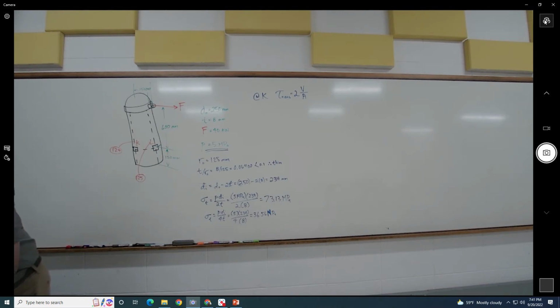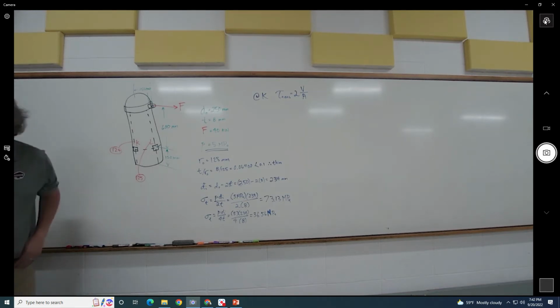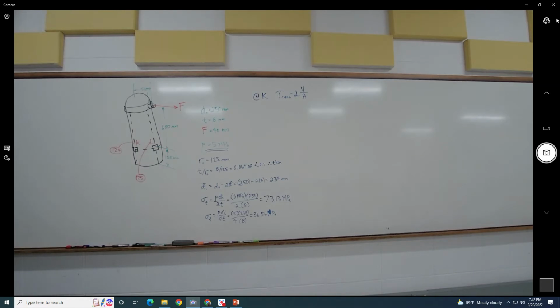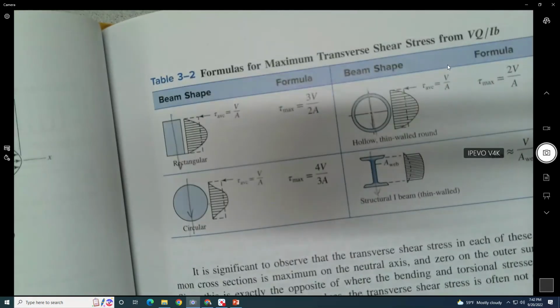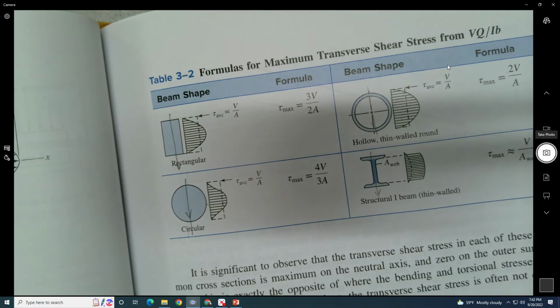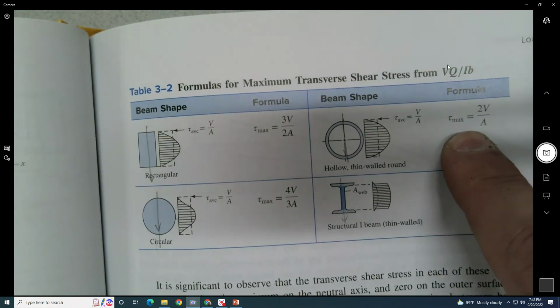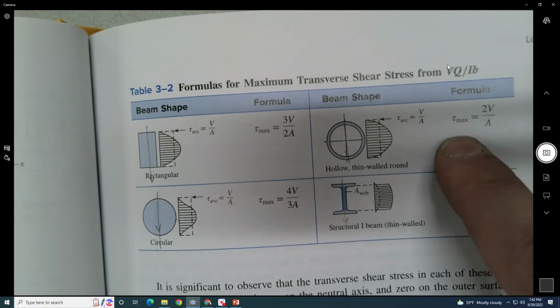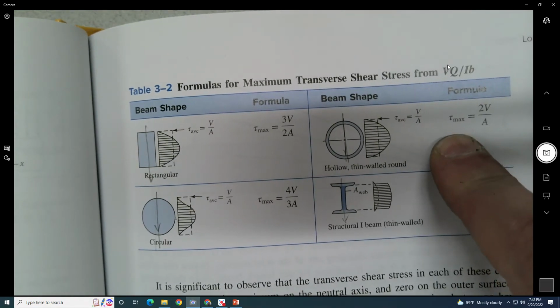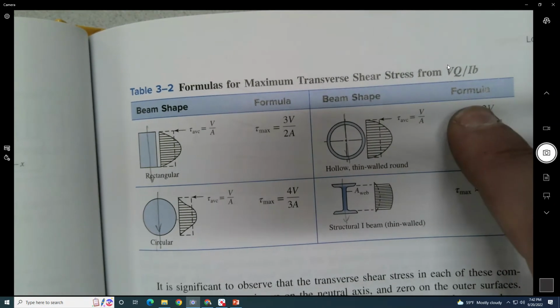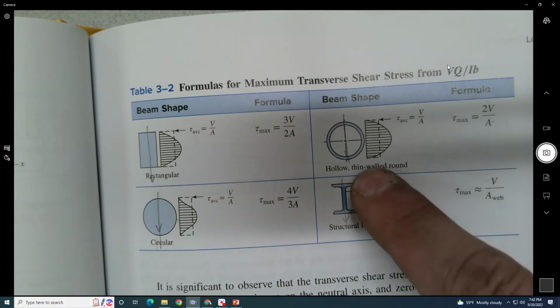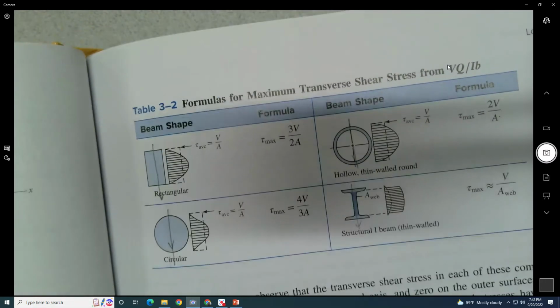So what does the subscript T and L stand for in the shear? The T is for tangential, which is also known as hoop. I like the name hoop better. But we got the maximum shear here. By the way, the L is longitudinal. So we have tangential as the T, longitudinal as L. And this right here is where we got it for the shear diagram.